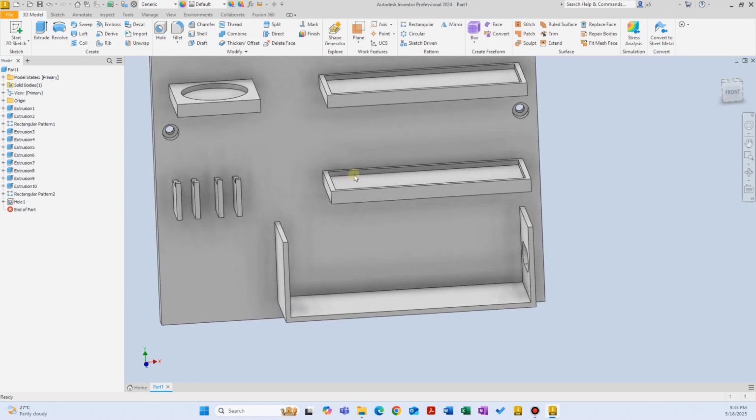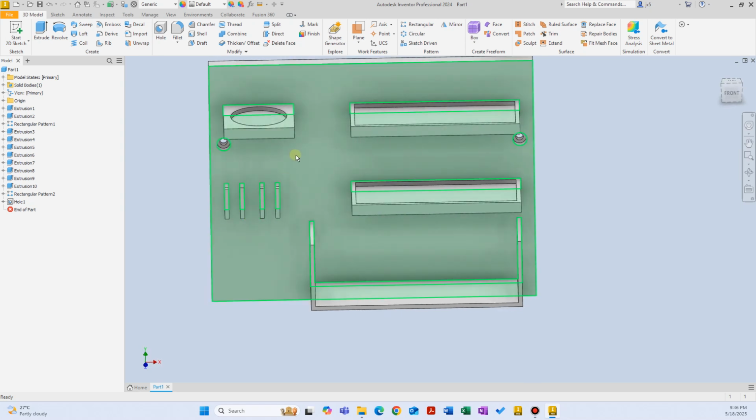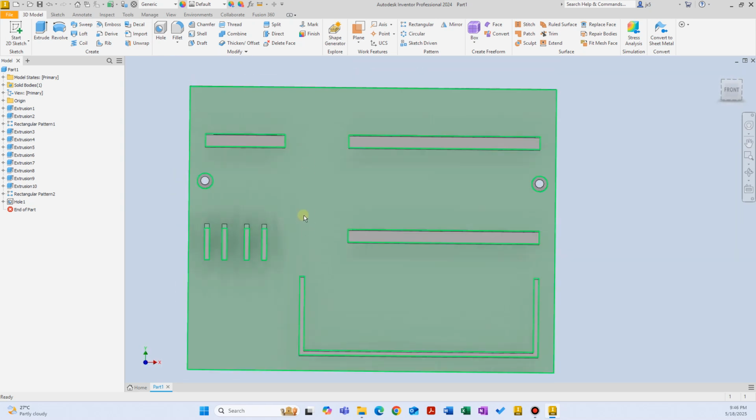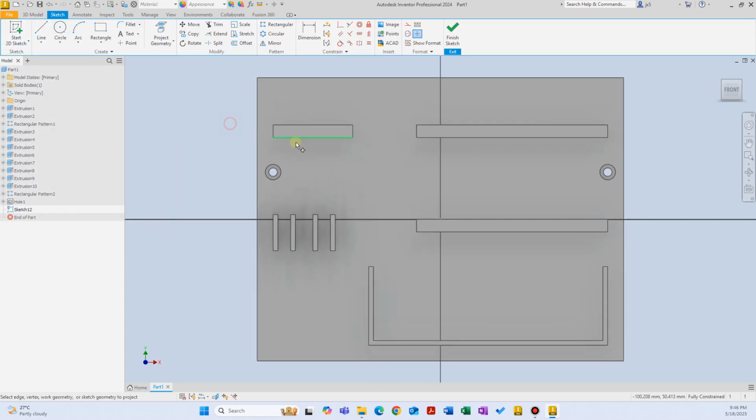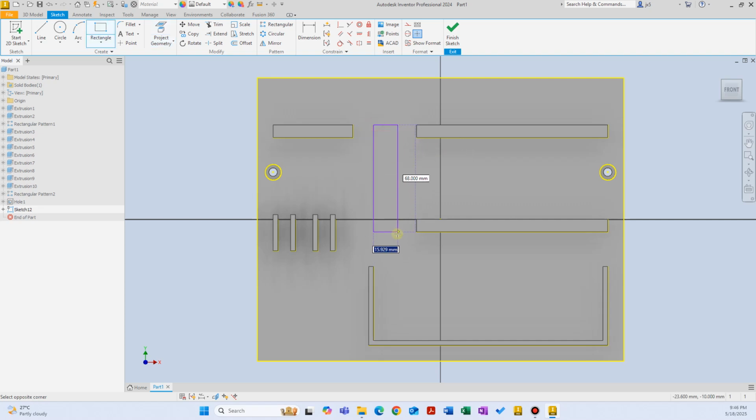Oh yeah, since we're going to put some shaving items here, and we have the toothbrush here, maybe a separator in between is a good idea. Let's just right click, create a new sketch here, and right click, project geometry, and now let's just draw another rectangle here. That way we can just put a wall there in between so they are separated. Again, let's just take advantage of the constraints. Let's just constrain these two collinearly, and then again this edge with this edge.